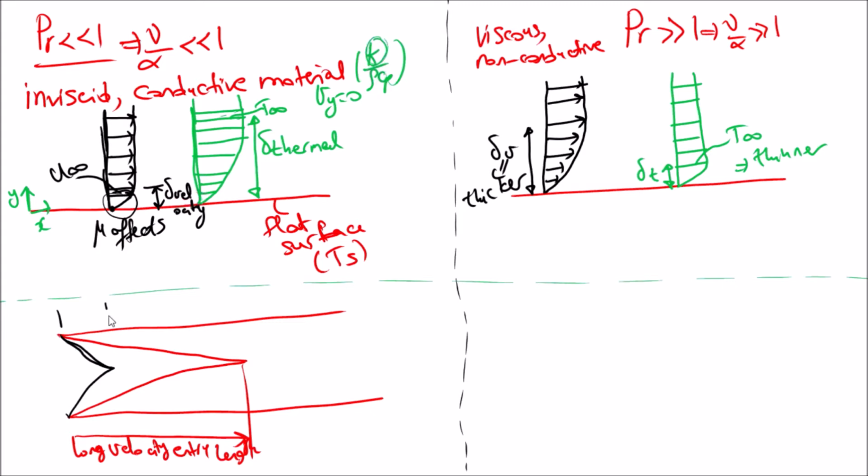Okay, this one is the short thermal entry length. Okay. What it means is that if the velocity entry length is long, we need a higher pump, because longer velocity length means a higher f value. Higher f value means higher pressure drop, and the higher pressure drop means that you need a more powerful pump. Okay, so it is a result of the power.